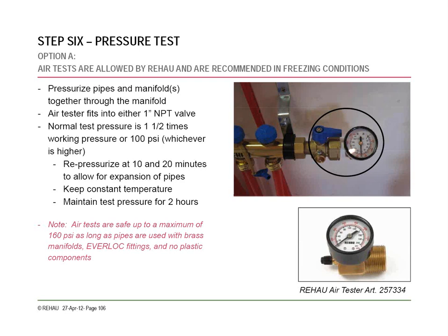You want to pressurize the first time, and then after like 10 minutes, pressurize it again. Make sure that it's up to pressure after the pipe's stretched out a little bit and everything's all set. Then you want to keep that pressure for 2 hours. And then you'll want to keep it under pressure again when you're actually pouring, so you'll be able to tell if they cut one of the tubes, so you can quickly repair it and then get it back under pressure.